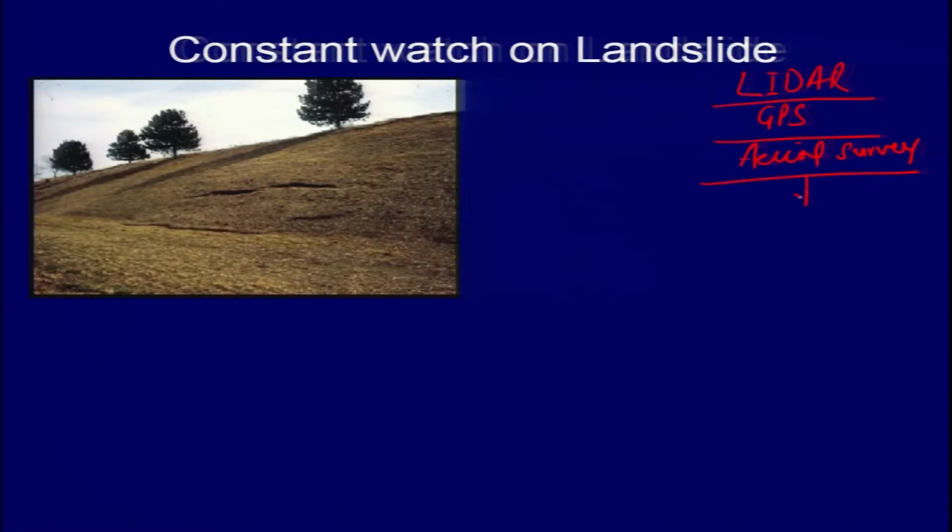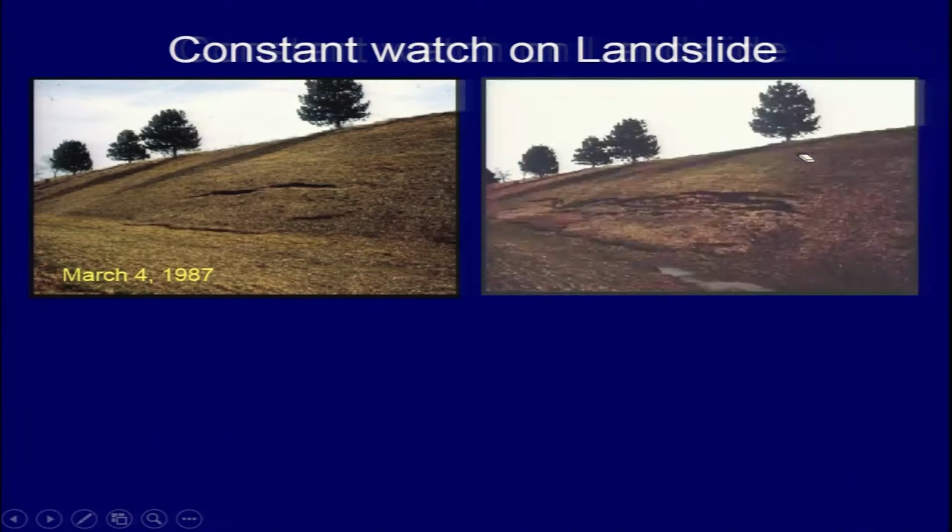And now, having the facilities available by UAV, one can do the mapping of the area which we suspect can experience landslip in future, and you can compare the photographs taken at different times or periods and try to understand what will be the scenario in future and what is the pace of the movement of landslide. Okay.